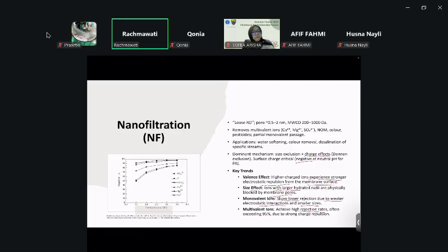So it's like still in the feed solution. Yeah. Which means that you might need to modify the chemical structure of the membrane that you are using, such as, for example, I'm going to use polyamide or I'm going to use another type of membrane. And you can think, do you have ions on the surface of the membrane, or should you introduce them? Should you modify it covalently and so on? It's basically like chemistry. Yeah.